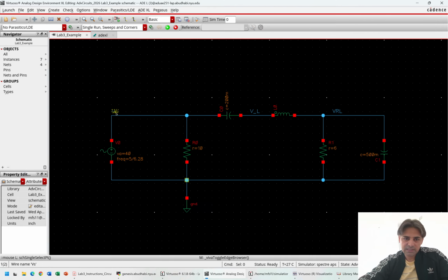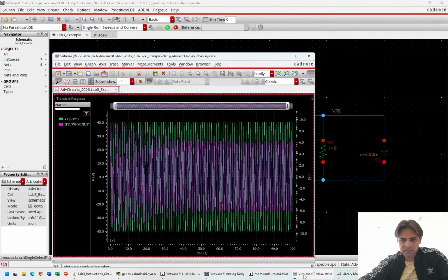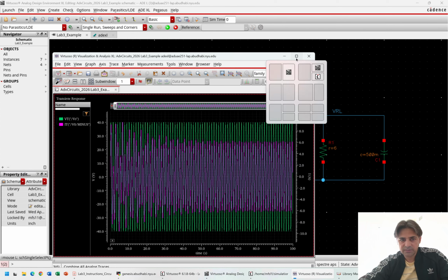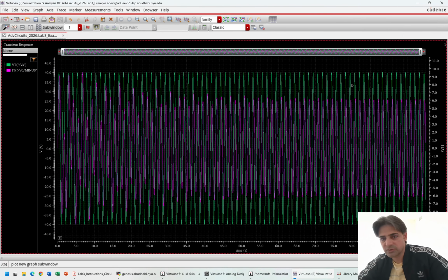So let's look at the voltage source. We know we've configured it to be 40 volts. So I'll click this one. This is the voltage and current. So current through the voltage source is going up. So I'll select this node here. Once these two signals are selected, I'll just hit the escape key and then I can see within this window these two signals. All right. I'm sorry, that direct plot was not okay.